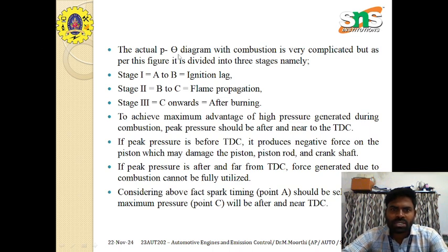The actual pressure theta diagram with combustion is very complicated, but as per this figure it is divided into three stages: first stage A to B, called ignition lag; second stage B to C, the flame propagation; and third stage, C onwards, the after burning.